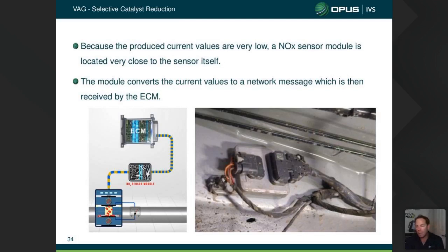You know, it is a little bit up out of harm's way, but they're using these same sensors on your Q7s. They're using them on the Volkswagen Touareg. So anyone that does a little bit of off-roady mud driving, these modules will be susceptible to water ingress. So keep an eye on them when you get them up on the hoist.